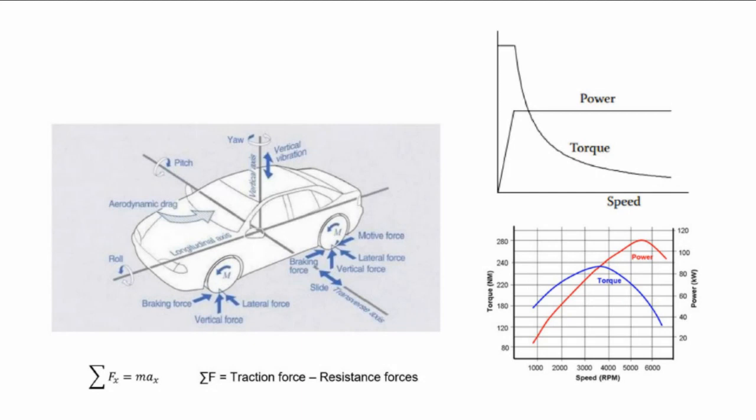In this chapter, the external forces that influence vehicle longitudinal dynamics will be studied in this course: aerodynamic drag, rolling resistance force, gravitational force, and longitudinal tire force. Generally, in an electric drive system, we start with the mechanical needs. After that, we can select our electric motor and drive system. This is a very important point.